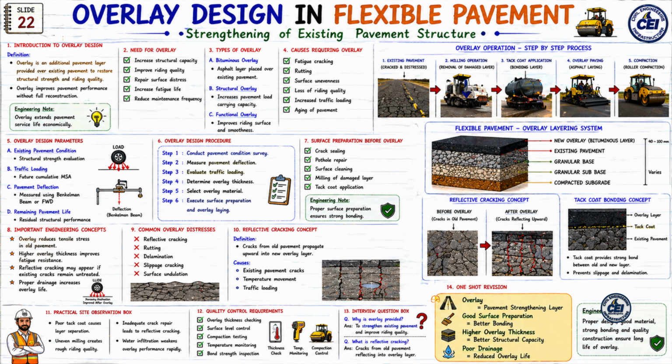Now let's look at the interview question box. Q. Why is overlay provided? Answer. To strengthen existing pavement and improve riding quality. Q. What is reflective cracking? Answer. Cracks from old pavement reflecting into overlay layer.